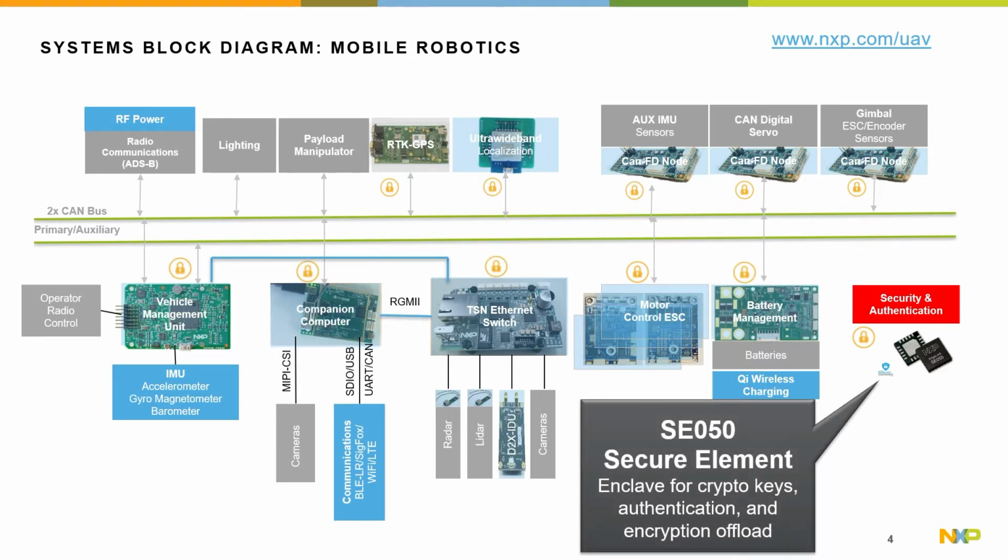I wanted to also highlight that on most of our products, the majority of our products, we include some form of secure element. And SE050 is one of the more public, easy to use, supported secure elements. It's a hardware enclave for cryptographic keys, encryption algorithms, and it can provide even backup or additional support in an already secure system.